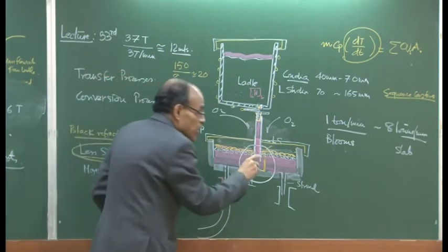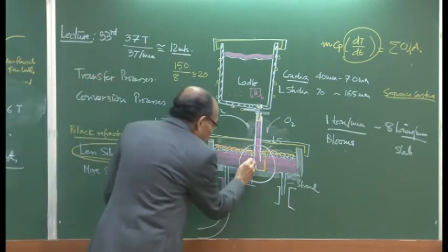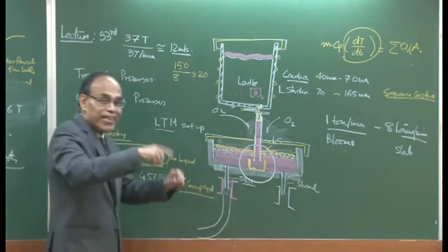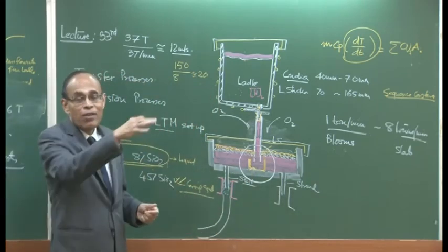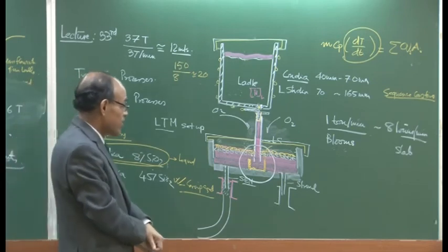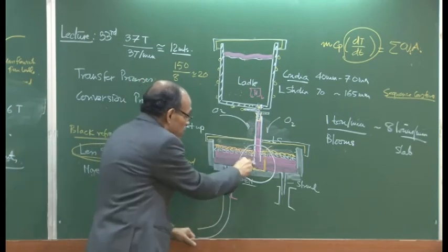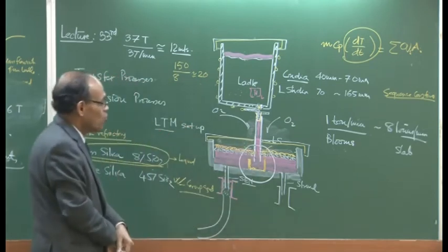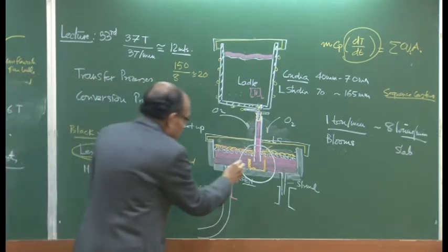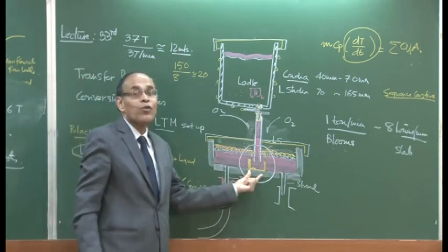In this particular case, you simply have more surfaces created by producing serrated designs on the surface, so that the surface area for frictional forces between the solid and the liquid becomes larger, resulting in slowing of the fluid, and as a result the slag metal mixing etc. is going to be smaller in this particular region itself. So most of the tundishes are going to be operated with a pouring box. This is called a pouring box.